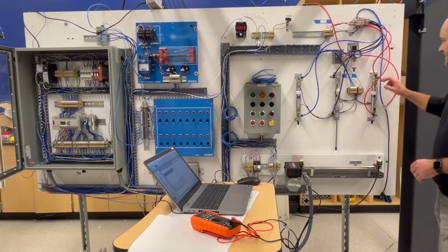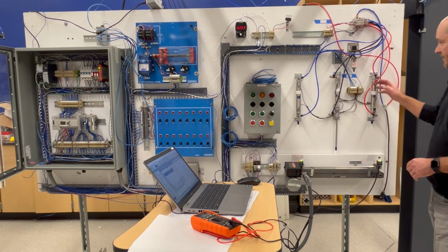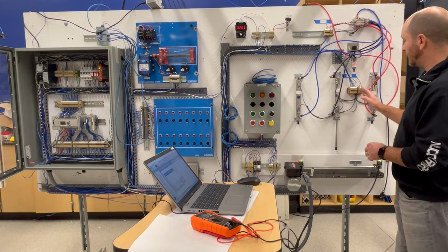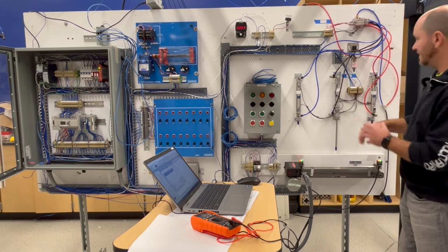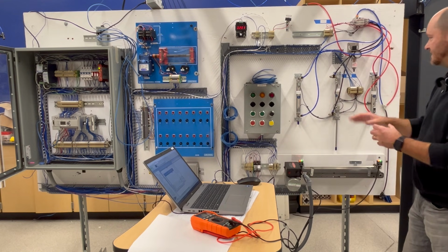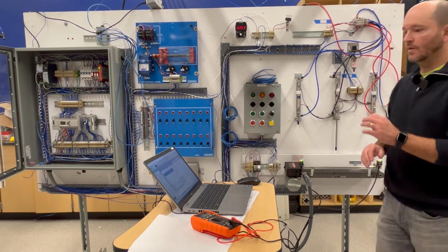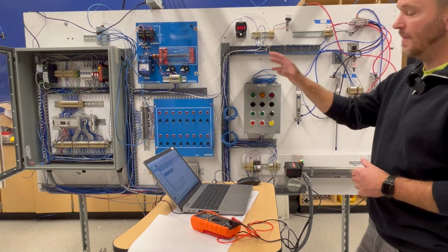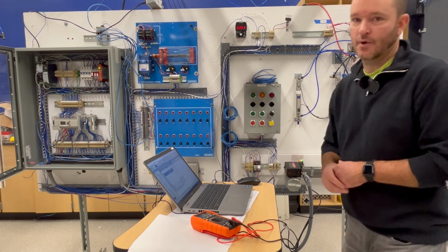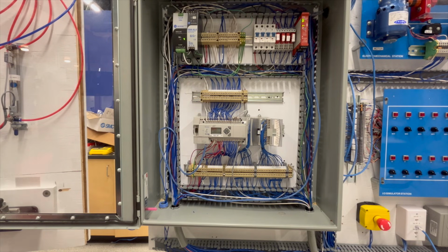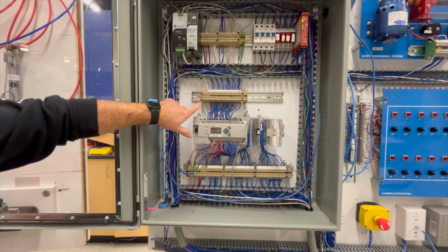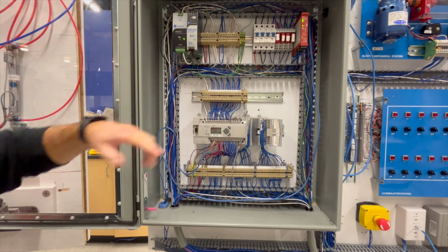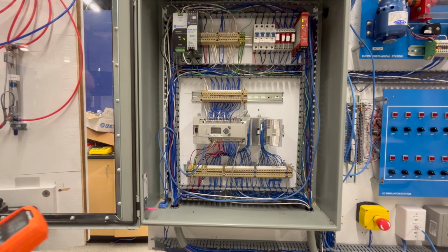What that tells me is that there is voltage coming to these 2. Now if there was a common jump that was going to supply all of these down to here, then I'd be like, okay, let's try to fix that. But instead, I'm going to go look at the common. So I'm going to zoom in on my control panel here to begin the troubleshooting process. Okay, so my feeling tells me that the culprit is somewhere in this common area, or what we would call our 0 voltage for our 24 volts.